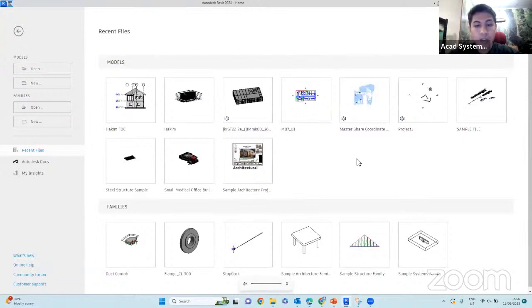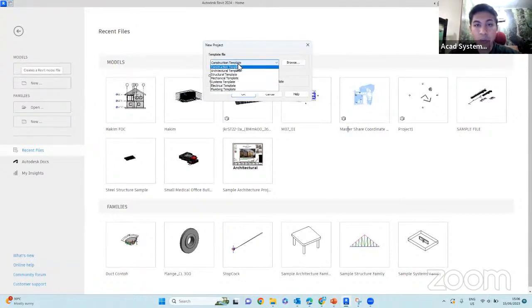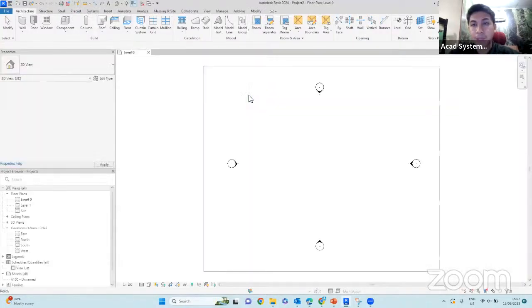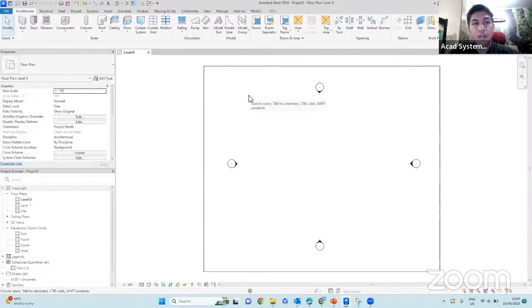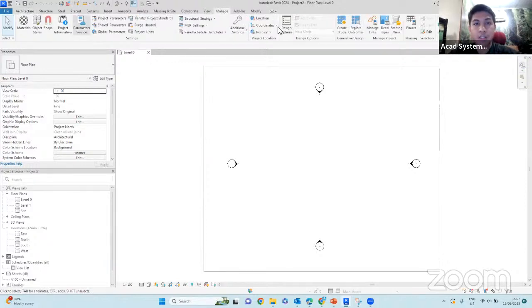Here is my Revit. I will just start off my Revit as we would normally do. I'll just use this template. Start up Revit, and then to access Dynamo, you go to the Manage tab in your ribbon. On the far right, we have the visual programming panel, and there's Dynamo here. So you can click on Dynamo.